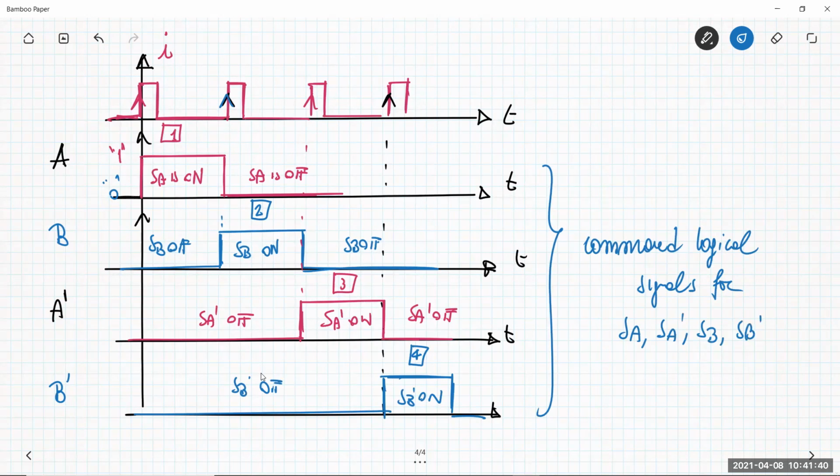When the command signal is 1, the switch is fully conducting. When the command signal is 0, the switch is fully open. And so there is this correspondence with the input pulses you provided. Of course, this sequence is for clockwise rotation.